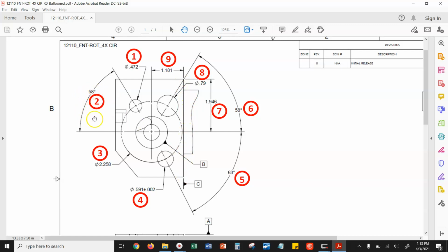Right, so this looks like it's simple enough. We just have to touch that circle and then output an angle in between this central circle and this outer circle here directly off the x-axis. So it's kind of applying what we learned last week, learning a couple new things. We have a 2.258 bolt hole circle dimension, so that's new. We're going to have to use the recall function.